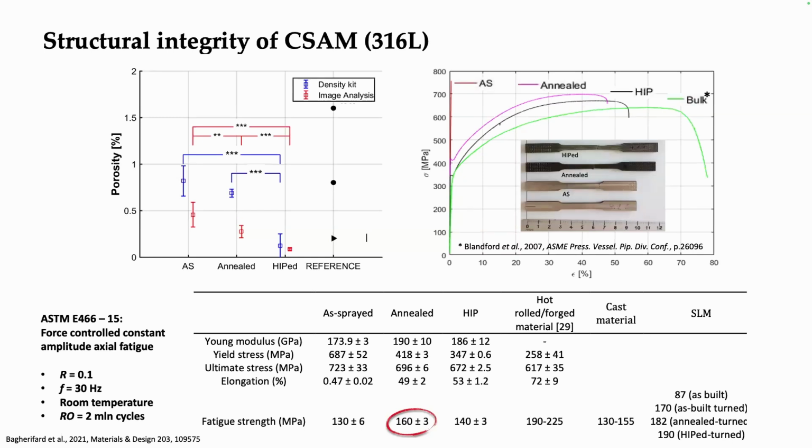And in terms of fatigue performance, again actual fatigue performance at 0.1 stress ratio, we got very interesting results. I have compared this with the data available for the same material made by rolling, or forged material, or cast or SLM material. Of course, it's not a direct numerical comparison, because the samples that I could find in the literature have different post-treatments.